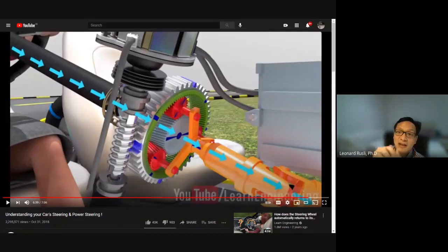It becomes a closed loop feedback that is always on, right? When you put in more effort, it immediately helps more, but not excessively. It can't turn it more than you want, right? So it becomes a real challenge, but it's definitely possible, okay? And this planetary gear set also allows for motor failure, and you can still drive it manually with your effort, okay?